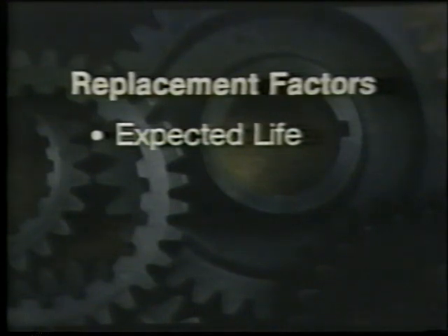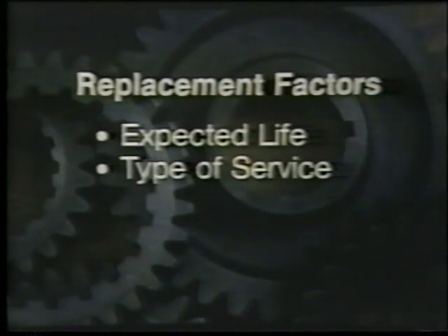The first thing to think about is how much longer the transmission is expected to be in service. The second factor is the kind of service. For example, in a transmission that is expected to give 500,000 miles of service, you find moderate pitting of the main drive gear at 300,000 miles. If there is not a noise complaint and the transmission is going back into the same operation, there should be no reason to replace the gear.